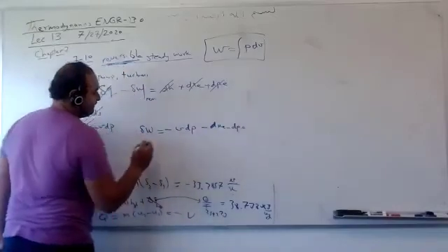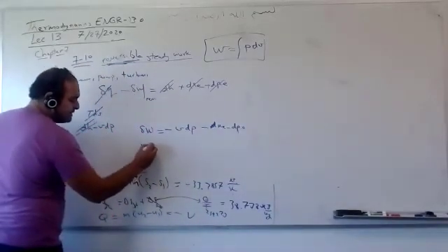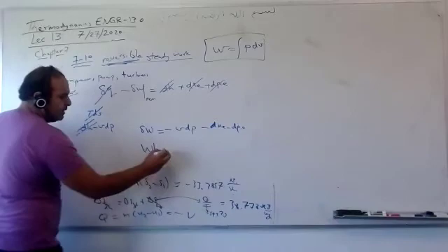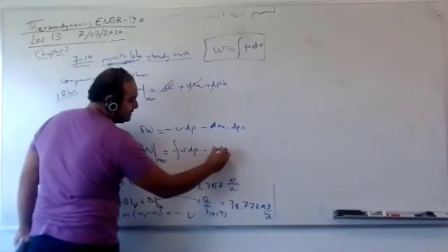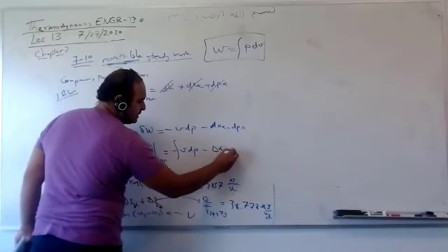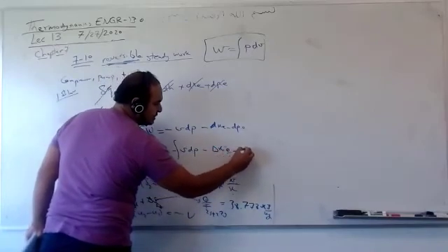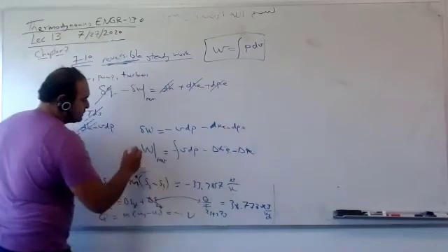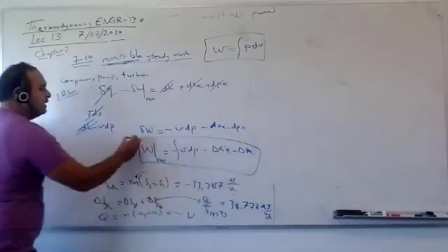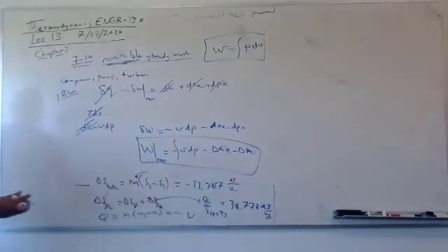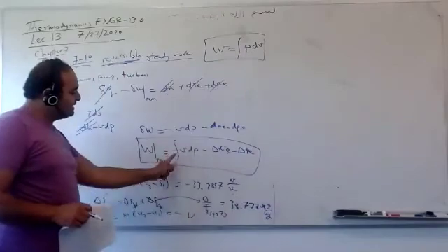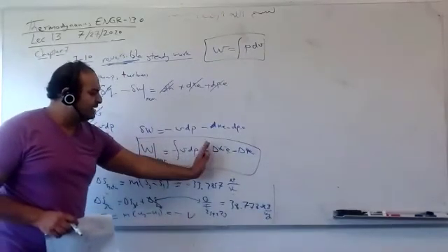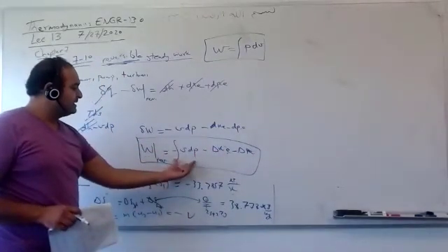If you keep them, it's okay. Or W reversible, only reversible, is the integration of VdP minus delta kinetic energy, small of course, minus delta potential energy, small. So this is called reversible work, only if you have a reversible process. Minus VdP. So this is PdV, always correct. This is minus VdP. Usually we neglect those, but keep them now. This is, guys, VdP.